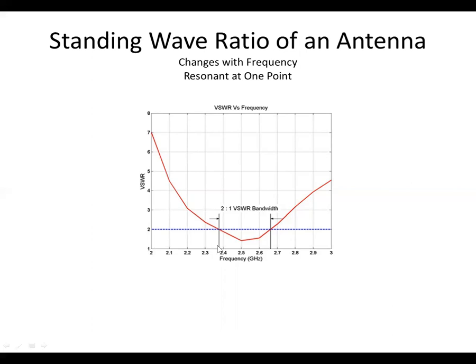Ideally, you would want a standing wave ratio of 1 all across the frequency, theoretically. But because of this interaction between the capacitive and inductive reactance and the frequency, you can't get that. As you change the frequency, on this side the capacitive reactance becomes dominant, and when you go higher in frequency, the inductive reactance becomes dominant, and it forces reflection of the energy you're trying to transmit back to the transceiver.